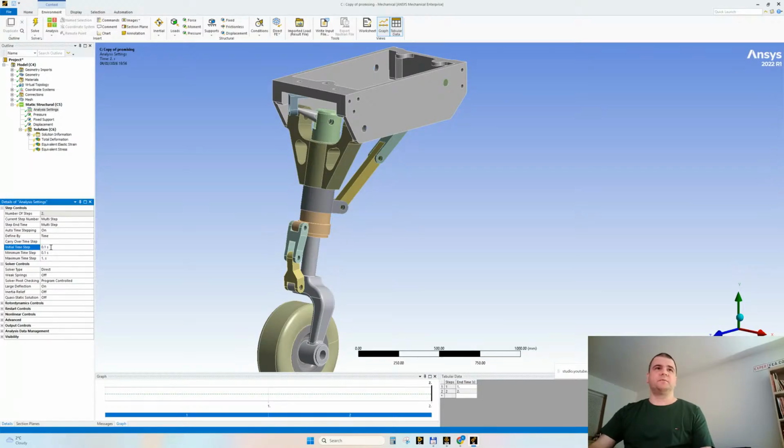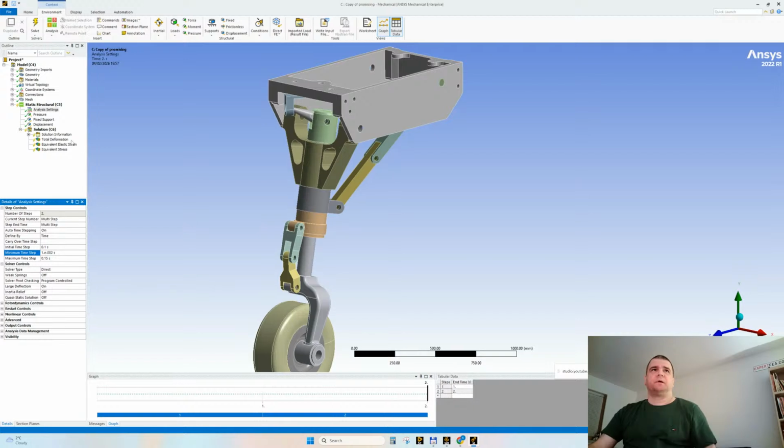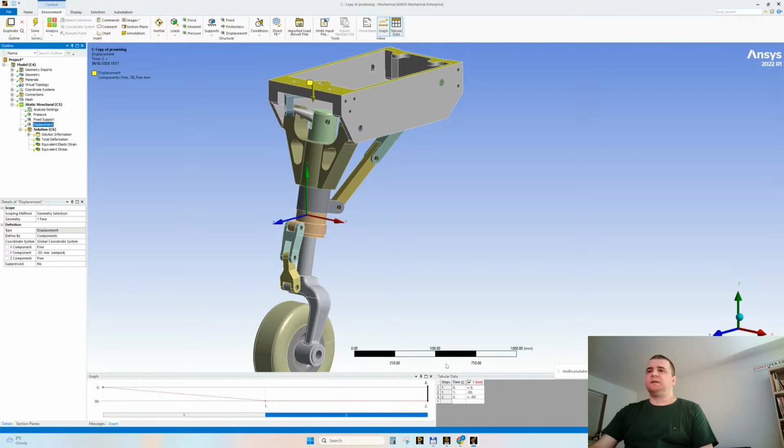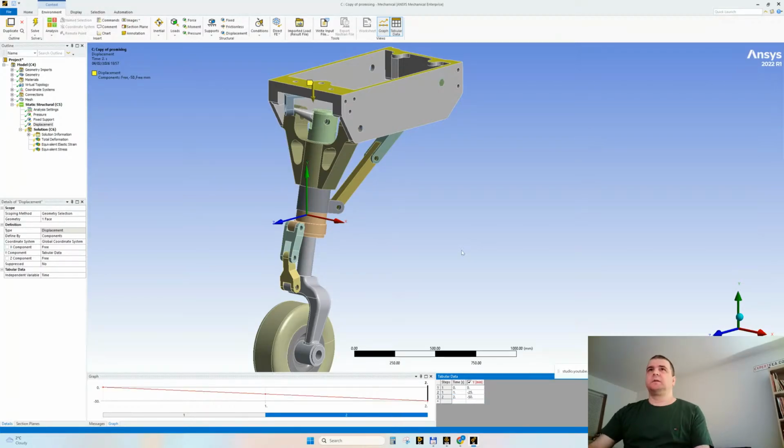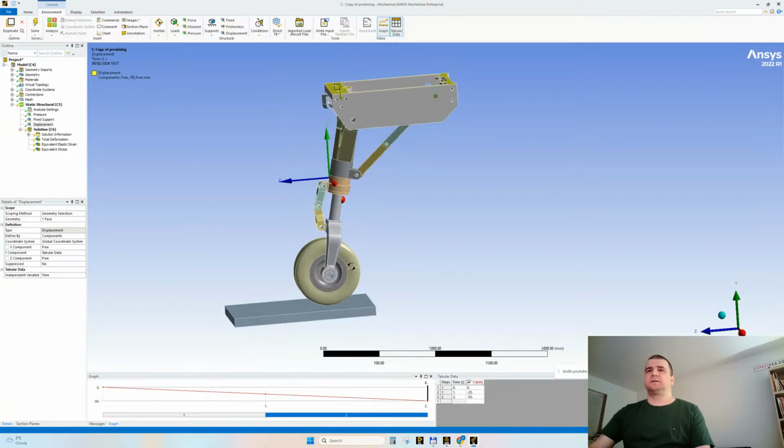We will begin with 0.1, 0.01, even though we have the rubber. Let's make it like this. I predict that the rubber will impose a very small time increment and time step. All right, and here let's make it gradually, minus 25 and minus 50.